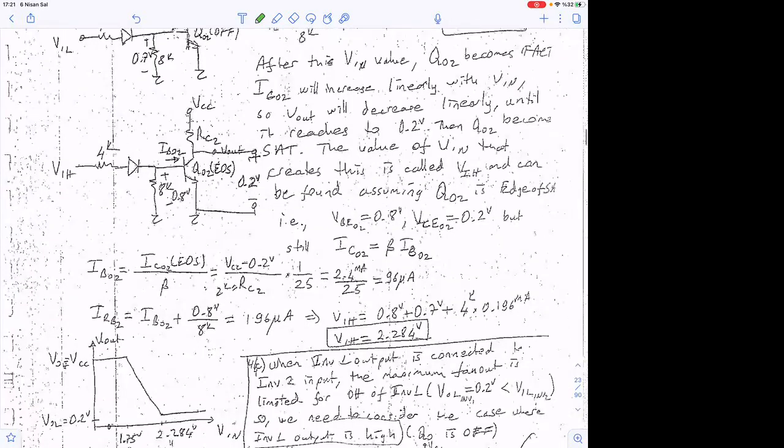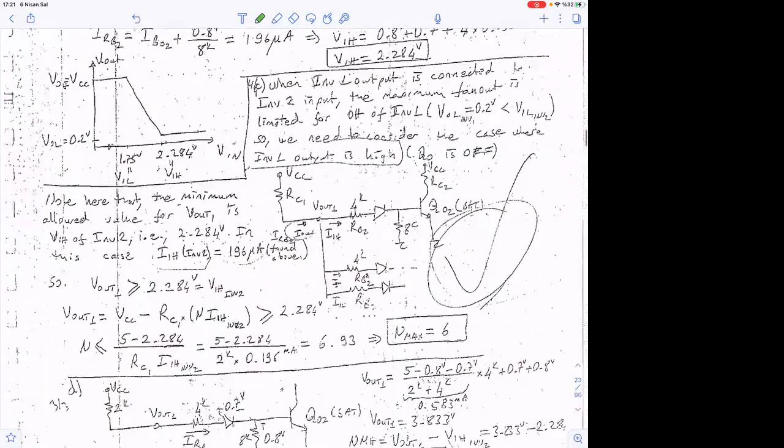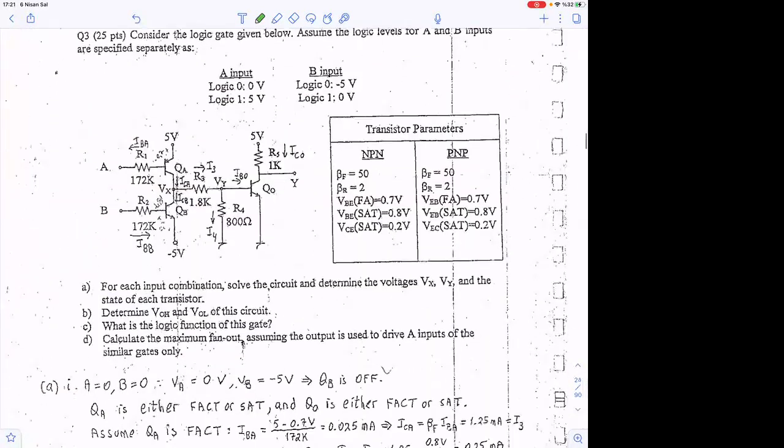We ask for the voltage transfer function. What about the fan out for the output low case, output high case? And what about the power dissipation? So that's kind of it. The only thing is that sometimes we give creative circuits like this, which you have not been faced with in the past. So you may need to spend a couple of minutes to understand the operation in general.